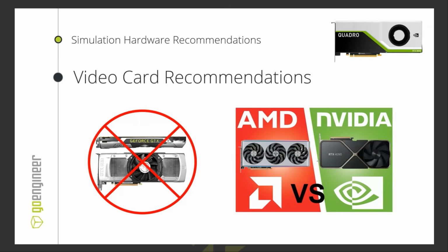I used to do tech support. Just a real quick comment there, Bill. Sure. Years ago, when it comes to video card related issues in tech support with SolidWorks, I would have anywhere from no issues or running just a little slower to not even opening or crashing SolidWorks when you're trying to open the software. So it could really be a video card graphics issue.